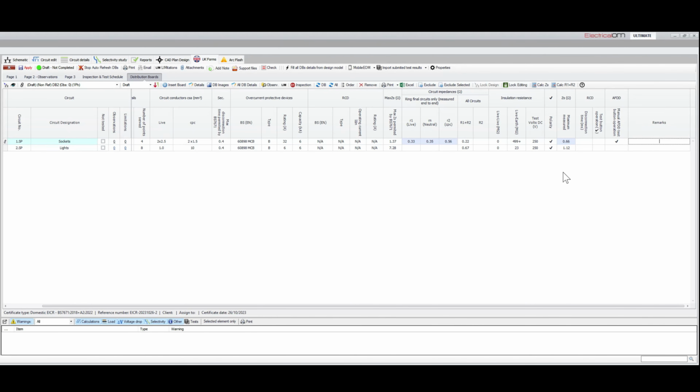However, within the lighting circuit, where there's a bit more electronics, you've got that emergency light, which has got a PCB in it, and there's the fan as well that's got a PCB in there, along with some of the lamps that would be LED with drivers and such. There is always leakage back to earth just naturally in the way those are set up at an electronics level. So you're going to see a bit of a lower value on your live to earth paths.